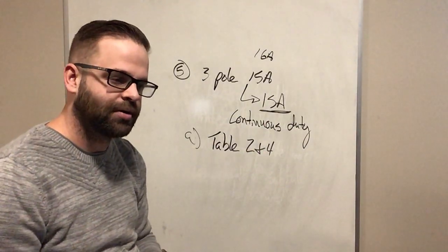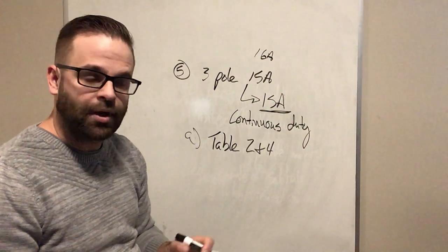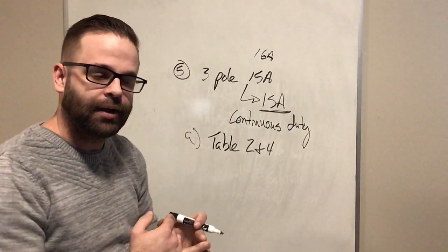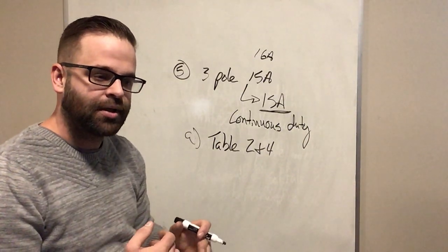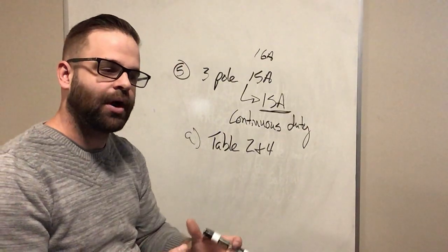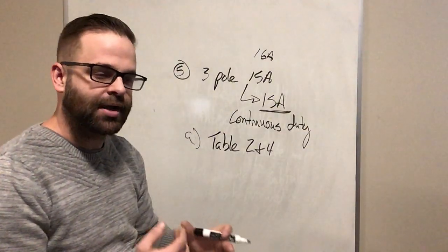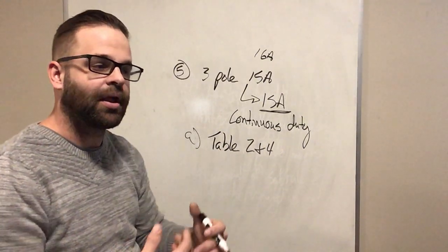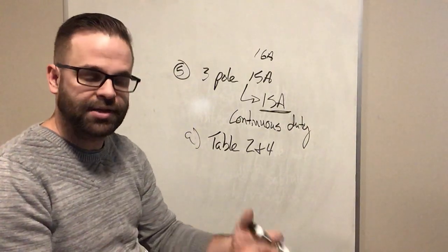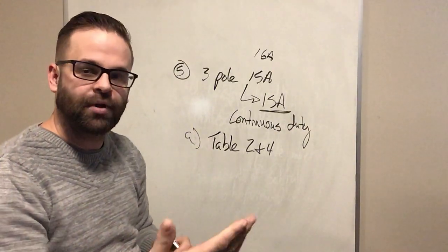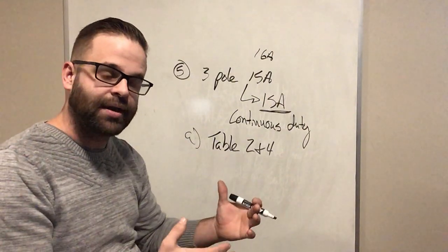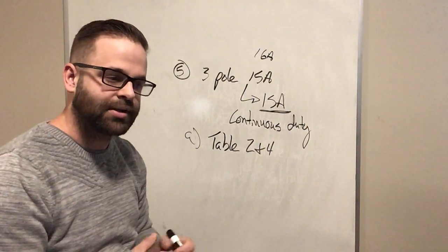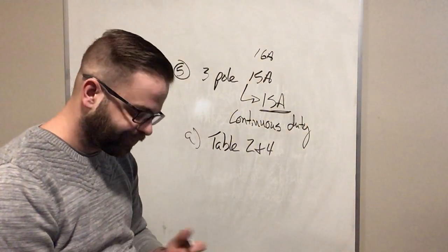With everything you're looking at when you're sizing things, you always want to protect that wire. You never want that wire to overheat. So the size of the wire chosen and the size of the breaker chosen are always picked to at least supply to the load what's needed to be run, but then you never want to exceed the size of what your breaker can handle, and you never want to exceed the amount of current that wire can actually handle, because then that's when fires end up starting.